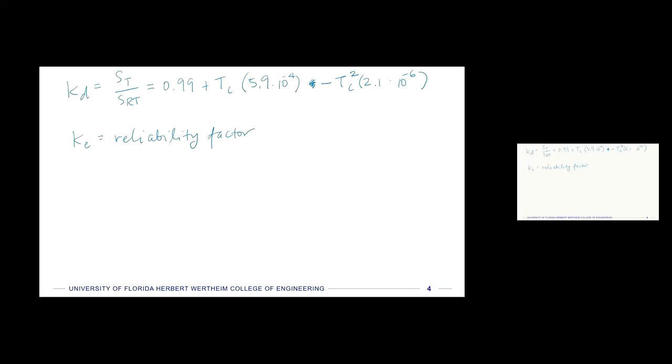So if we want to have very high reliability, then we want to go below our average of the S-N curves. And so it's going to drop the endurance limit down. And these are just taken from those normal distributions.